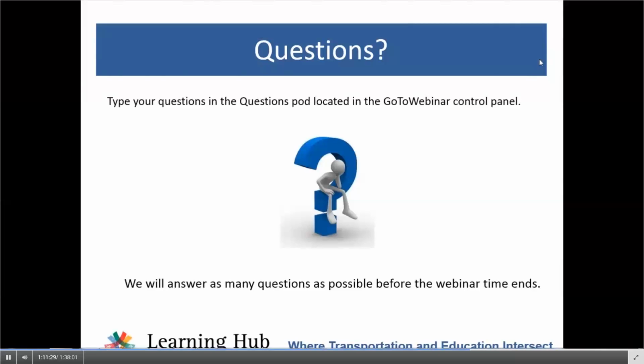Versus at a roundabout where the queue continually moves up, it's a more active waiting, and the thinking here is that therefore the delay experienced at a roundabout is more severe than that at a signal. And so that is maintained also for the interchange application.